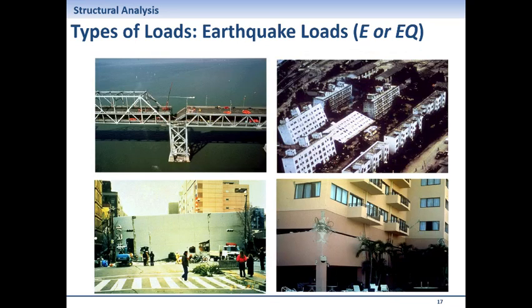This particular building, there was another story there. We refer to it as soft story, because in that building there's a combination of masonry walls and reinforced concrete frames, and during the earthquake, that column, probably 3 meters long, is completely gone. So you can see 2 floors now, well, 1 floor completely gone.